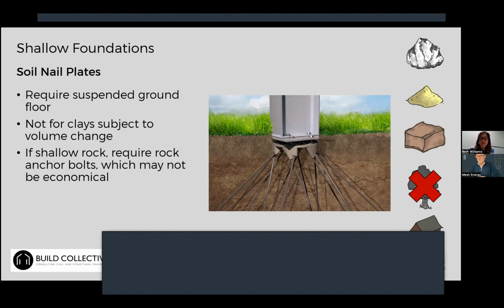It depends on what they came asking for. Often, for the more common example, when I do PassivHaus projects, a lot of people want to do insulated raft foundations, which are a really versatile foundation type because they're designed to deal with variable ground conditions. That's what a raft is useful for. When people come wanting to use screw piles, which is quite a common one, it's less common that they actually end up using that.